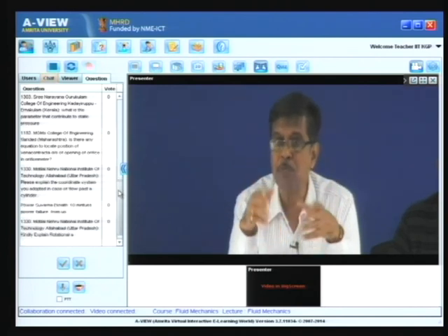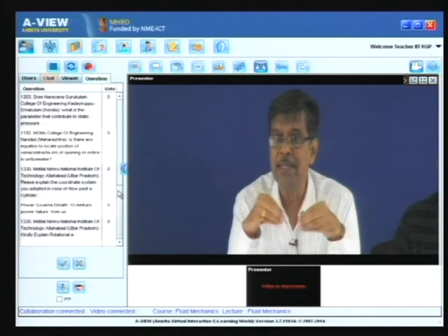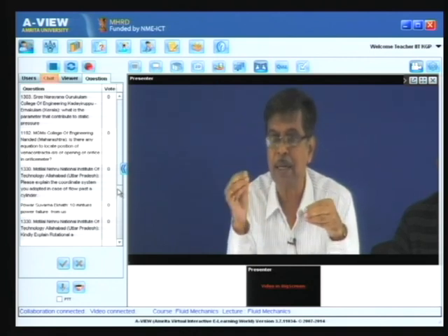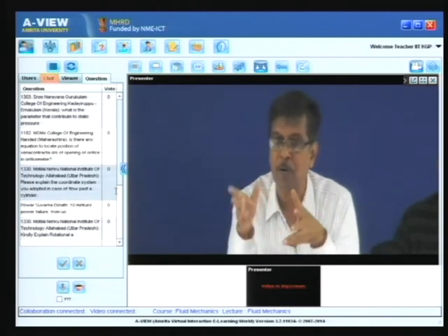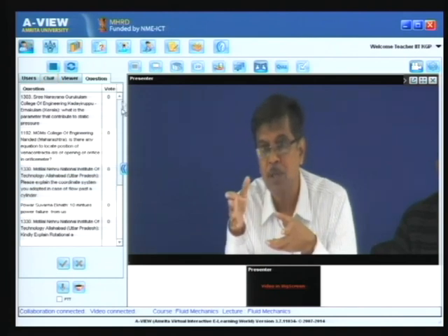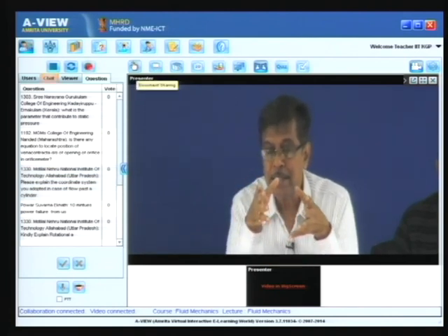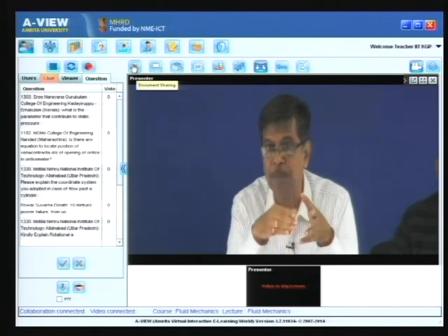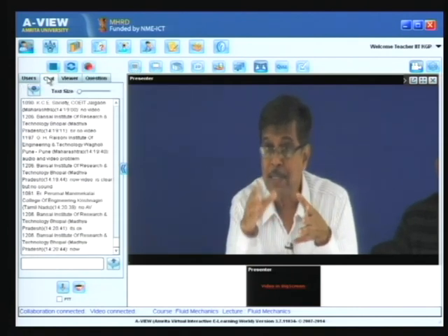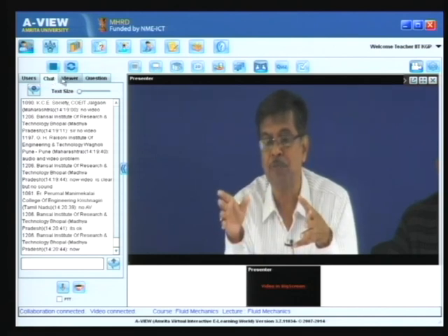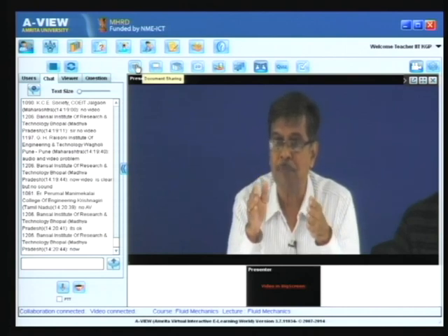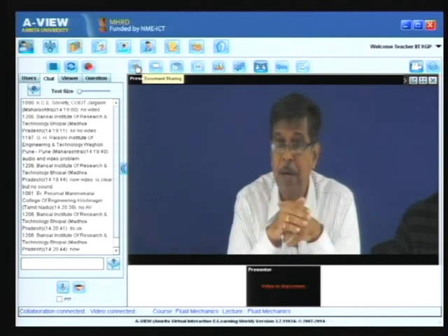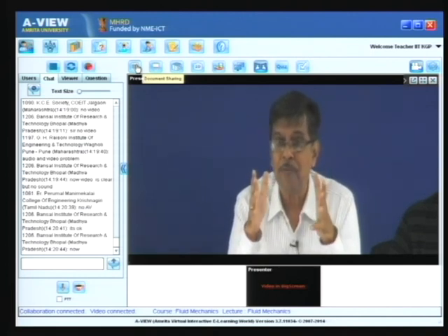A system always moves in a flow field to maintain its identity, just like the Lagrangian particle. Therefore, we cannot define the rate of change of momentum for all control volumes, because control volumes may be fixed or moving. So this statement of conservation of momentum refers to a system: the rate of change of momentum of a system equals the force acting on the system. The basic conservation laws of physics are all defined with respect to a system. But how do you relate these laws to a control volume?